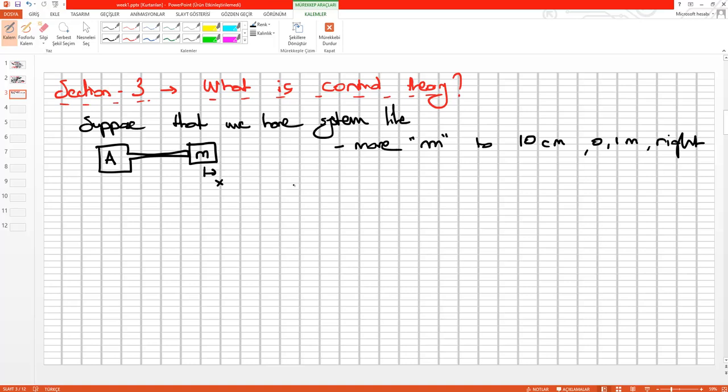Okay, this is the basic problem of controlling this system. In the normal case we have this information here. For example, if we want to utilize the transfer function domain, we should obtain the G(s), the plant formulation, and in this case what's the name of this output value here? Position, right? Position X(s), because we want to control these terms, so we need to set this transfer function to produce the position values, right?